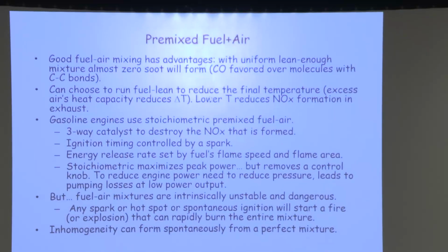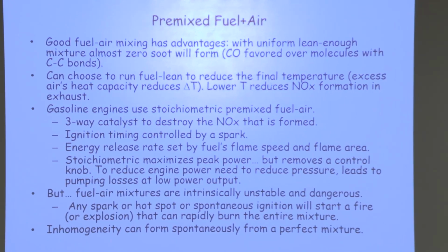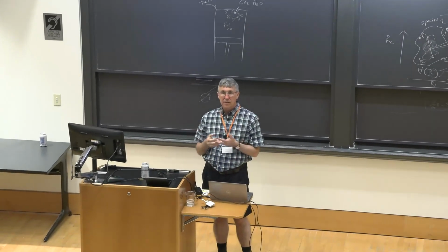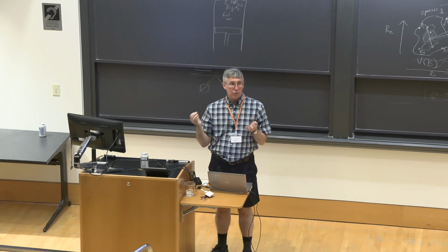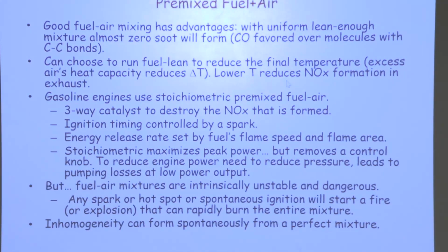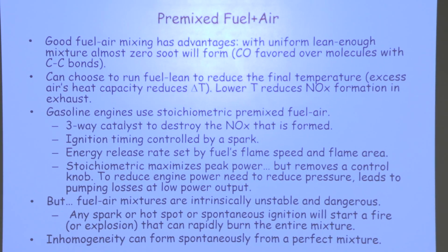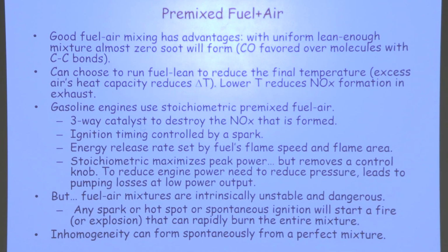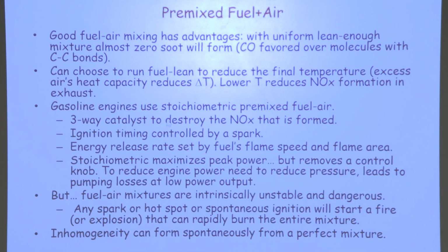And you can also add a lot of air, and that will reduce the final temperature because the nitrogen in the air gives extra heat capacity to make the temperature lower. And that will have the effect of reducing the amount of NOx you form, because NOx is a very high activation energy process. And so gasoline engines work this way. So they stoichiometrically mix up the fuel in the air. And then they make a lot of NOx because it's stoichiometric, the temperature is actually very high.